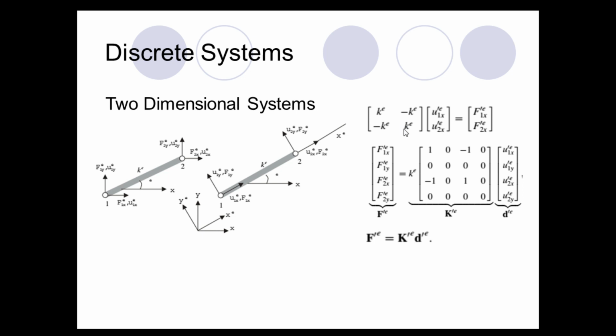Now in y direction I cannot write something because my stiffness, or in ye, okay, in ye, this is the coordinate system which is attached to the element. So in ye direction, forces have to be automatically 0, and I cannot write any relationship between the displacement in y direction or any displacement with the forces. So I cannot write any relationship.